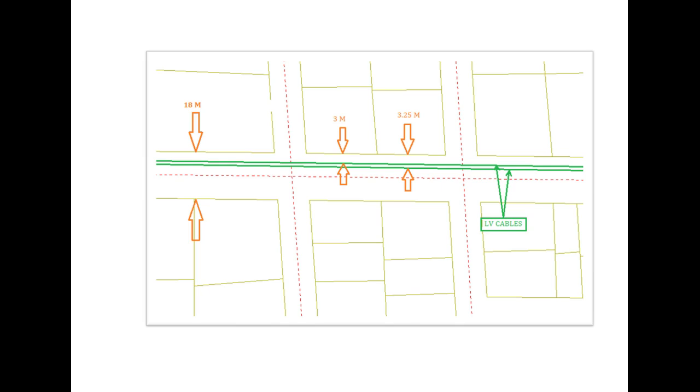If the number of LV cables is large and there is not enough space available between the first LV and first MV cable, 3 to 5 meters of space, then we can utilize the spare area between the first LV cable and the parcel to draw the additional cables. Picture 8. Case 2, street row width is less than 10 meters.